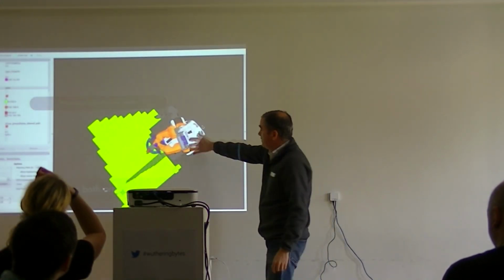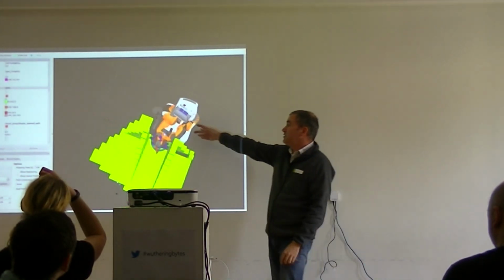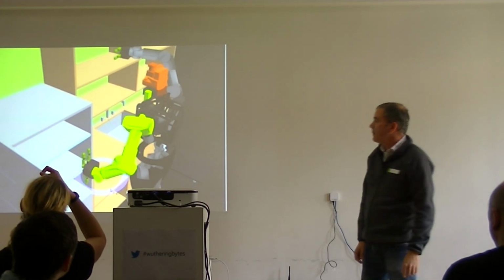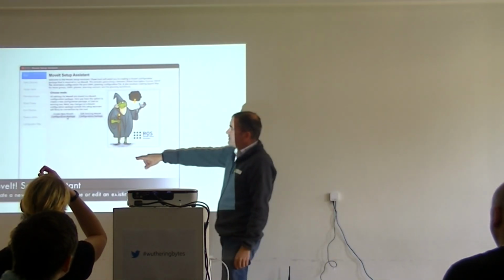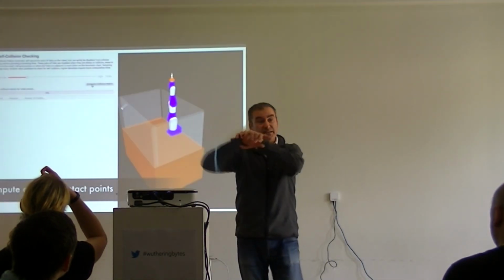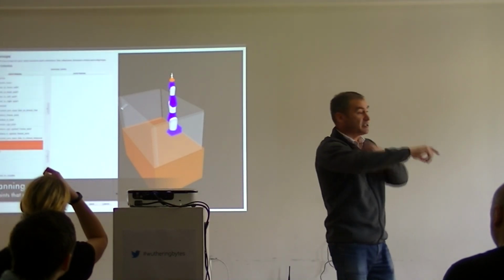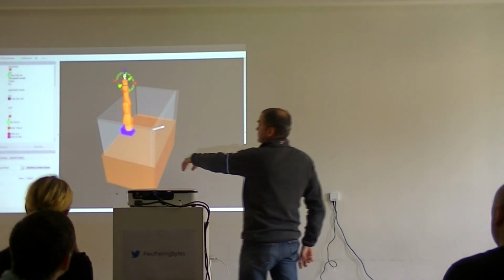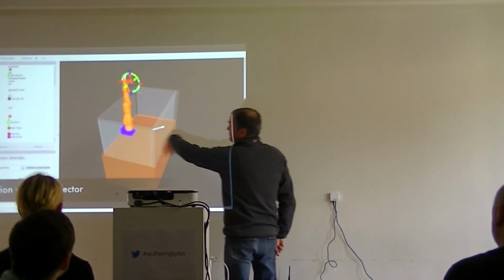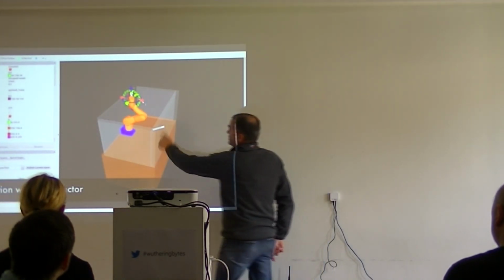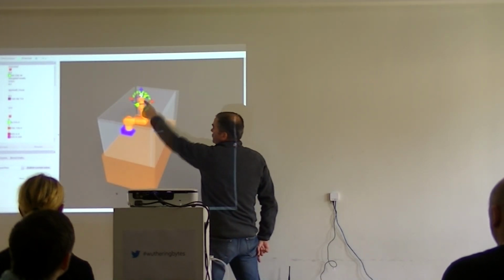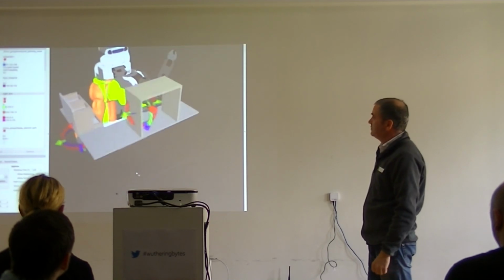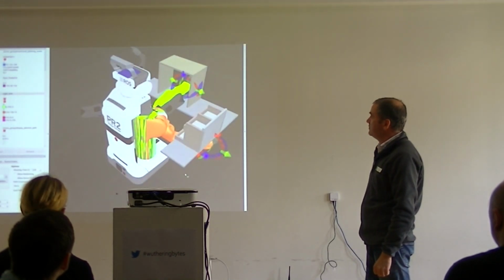So you can get visualizers. Once you've got the URDF, you can play around with something in a visualizer, and it can calculate the paths that it will take, and it will do collision avoidance on all the joints. So you can put in a visualization of the space that it's going to work in and say that you mustn't hit these bits, and then as you drag it around, it will calculate those paths. As environments for the robot to operate in.